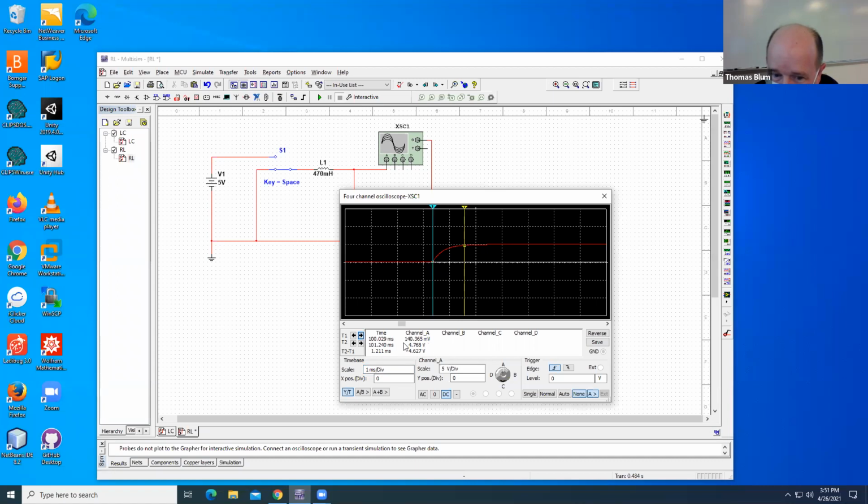I'm looking for it to change, and then I'm going to go back. It just changed to 140 millivolts. I'm going to go back. So that's the last time it was very small. I'll effectively call it 0. Okay. And then I'm going to go up to, it's the same math as it was before, 63% of 5. I'm going up to 5. You can see that this is 5 volts or 4.998. We're going to call it 5. And I want to go up to 63%. One time constant is 63%.